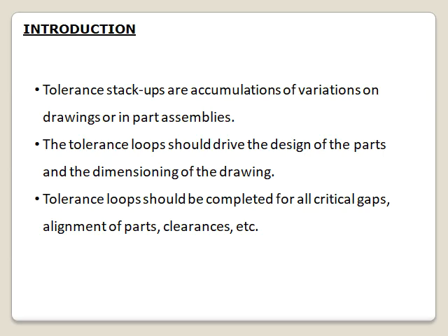This tolerance stack-up analysis will be done by looping mechanism, based on the design of the parts and dimensioning of the drawings. Tolerance loop should be completed for all critical gaps, alignments of the part, and clearances, which defines really how much tolerance we need to give for a part.